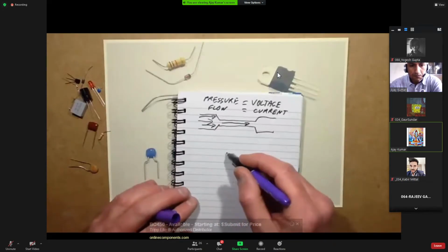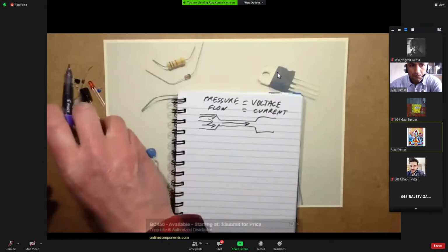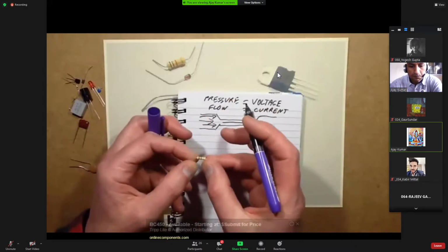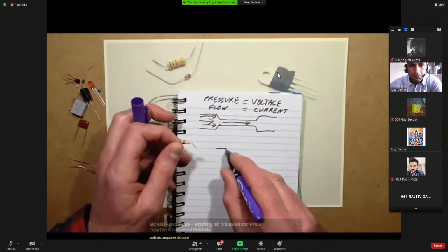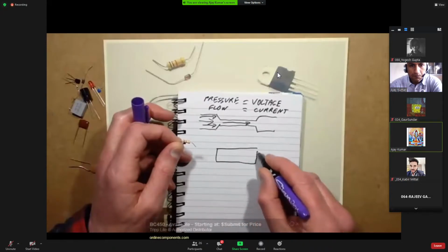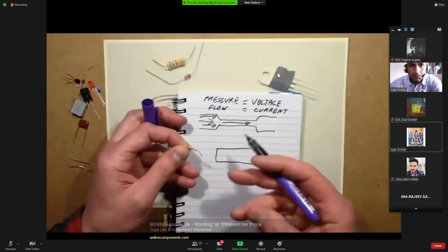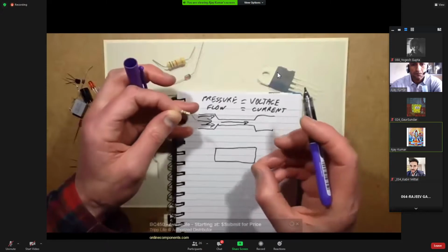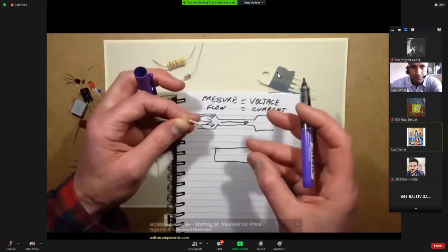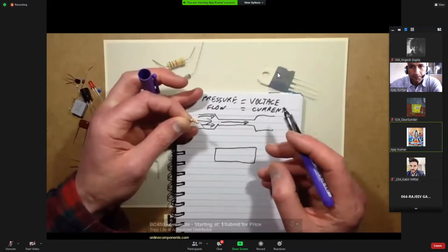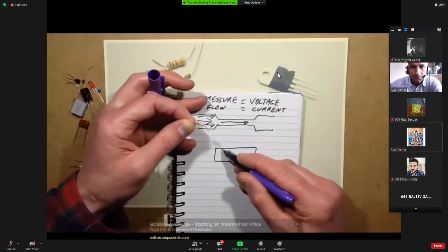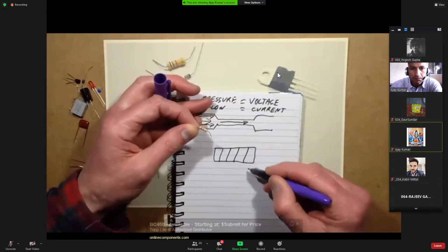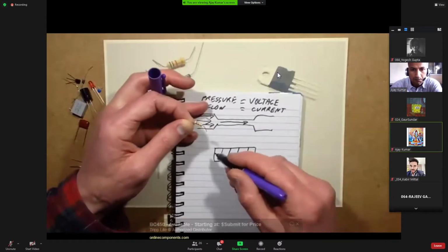Now, the construction of a resistor is usually, in the case of these ones, this is a carbon film resistor. And you get metal film, carbon film, wire wound, but one of the most common is just carbon film or the metal film. They have a little ceramic tube, which is coated with either a metallized coating or a carbon coating up to a specific thickness. The thicker the carbon coating and the type of the composition they're putting on it, the more conductive it will be. But then they can fine-tune that. They actually cut a spiral round it, and that creates a long, thin path of the carbon, and that increases the value of the resistance.